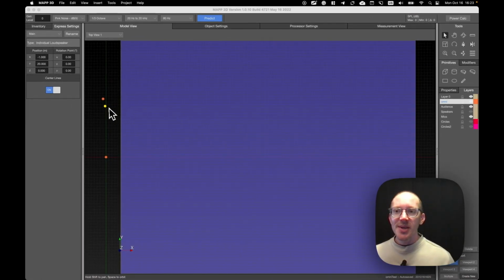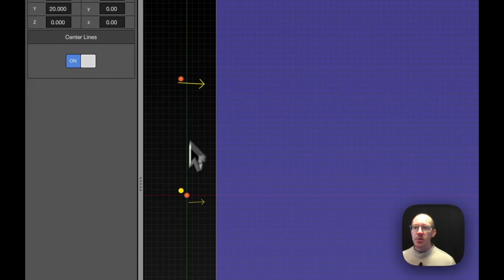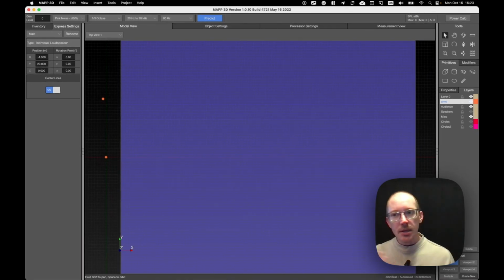So we could move the speaker again, but just talking about electronic resources like delay, we don't have a pre-delay to pre-delay this back this way, but we can delay this guy so that it's also 1 meter late. 1 meter is about 3 milliseconds.